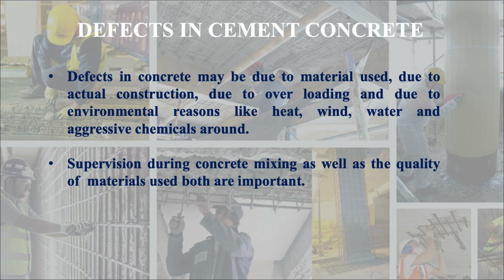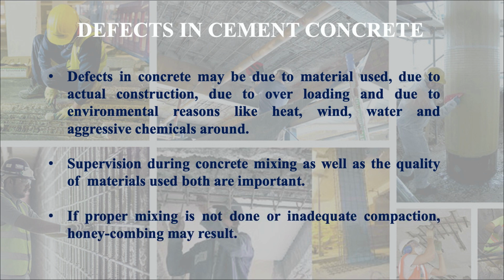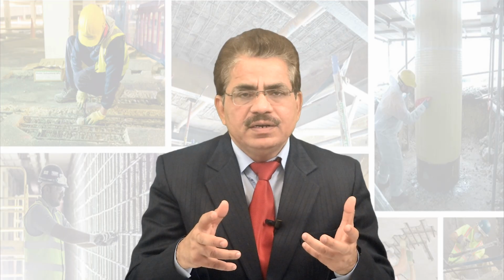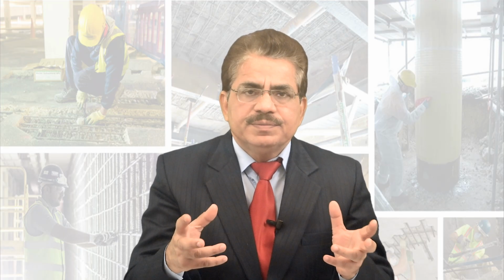It is not only supervision during concrete mixing that is important, but also the quality of the material used for preparation of the concrete. If proper mixing is not done or inadequate compaction is there, then it will result in honeycombing. In honeycombing, there are voids in the concrete, and voids in concrete mean it is a weak concrete. It will create many problems.